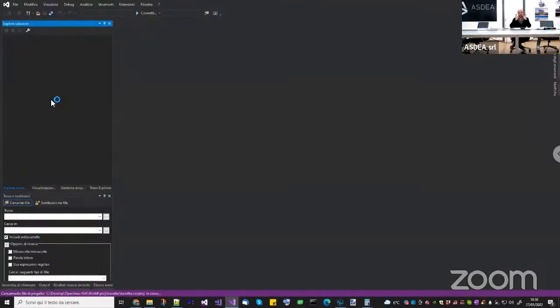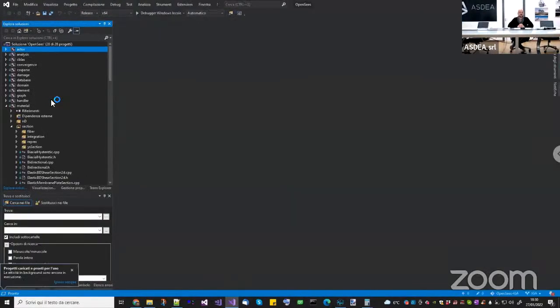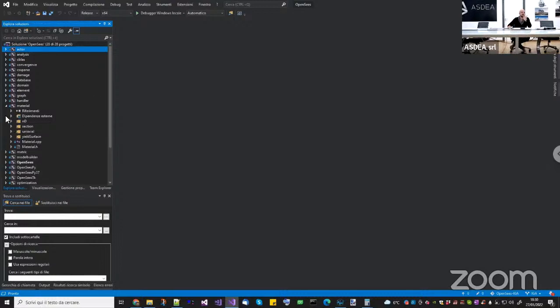because the main problem with updating the parameter is that you need to make sure that the element that you have is able to set the parameter. So for example, in your case, Lin, you want to update the Young's modulus of each shell element of a certain floor. So first of all, you need to understand if the shell element you are using supports the updating of parameters. Otherwise, it's not possible. In your case, the shell element is the ASD shell, right? Yes.